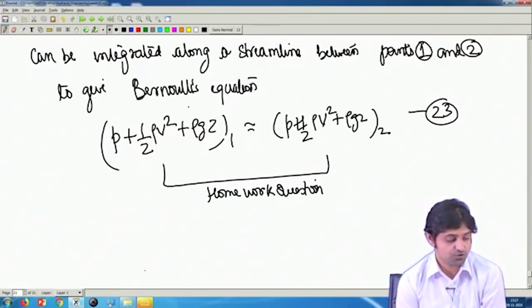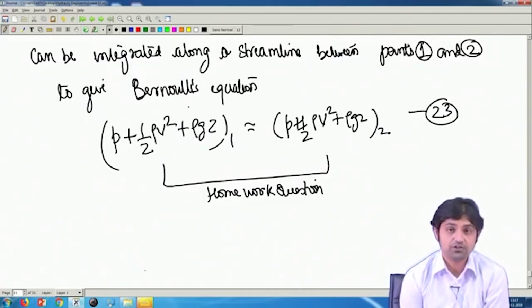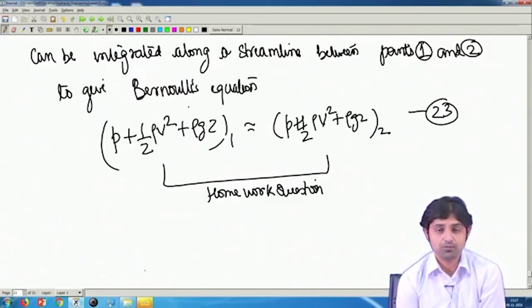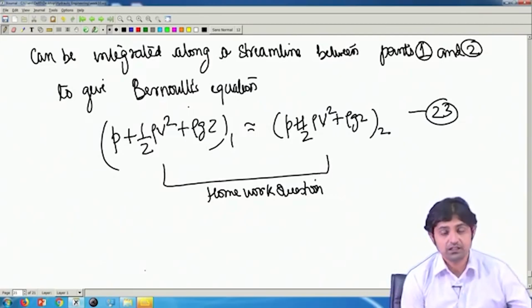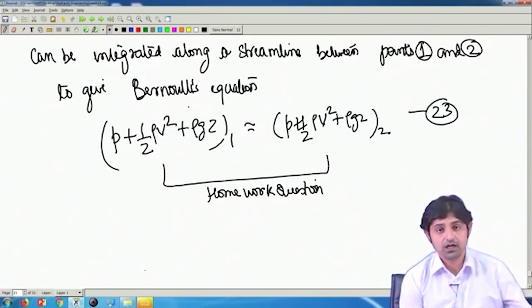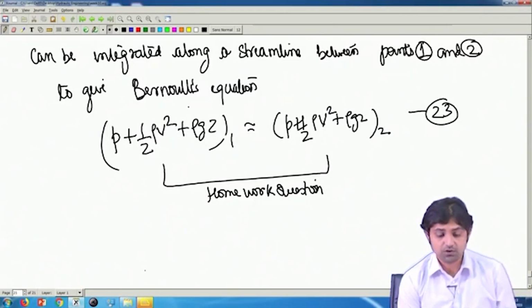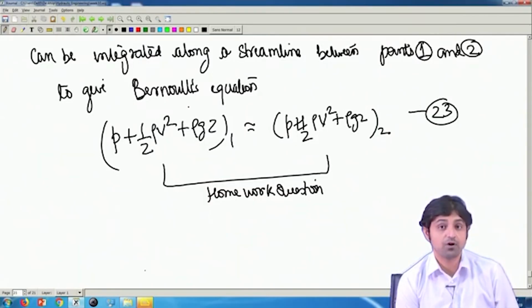We derived the Navier-Stokes equation. We also saw the difference between the thermal and the mechanical pressure and the conditions in which both can be the same. Then we simplified our general Navier-Stokes equation. That was the purpose of this module. Then we simplified it to obtain the Euler equation, and also how Bernoulli's equation is got. So, you also know the origin of Bernoulli's equation in its purest form.